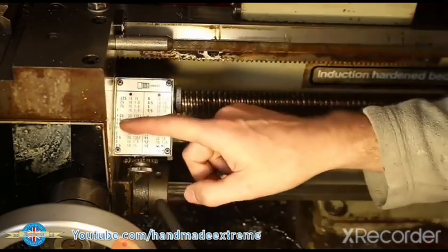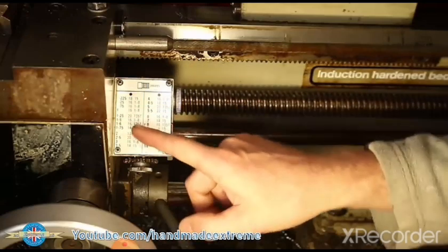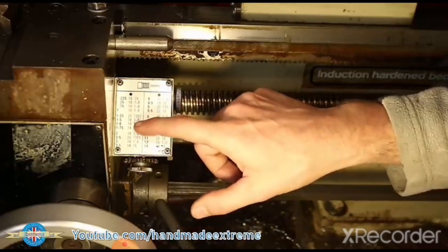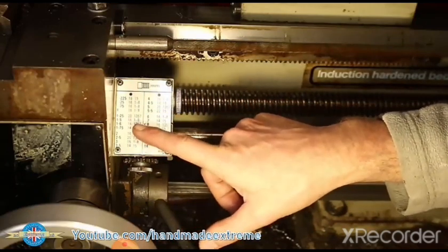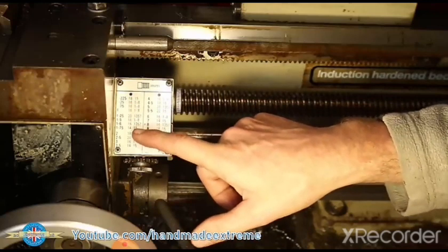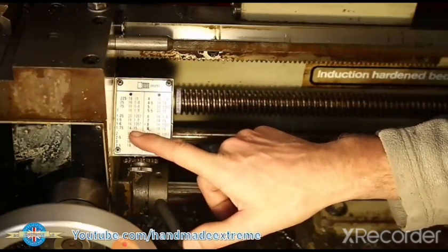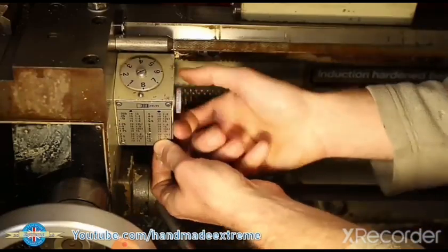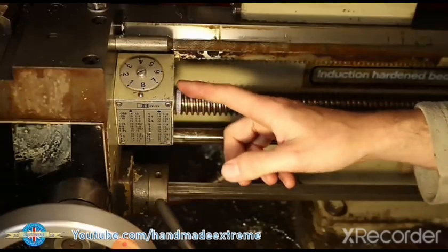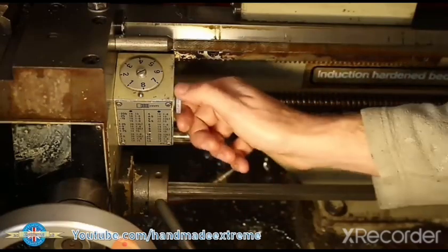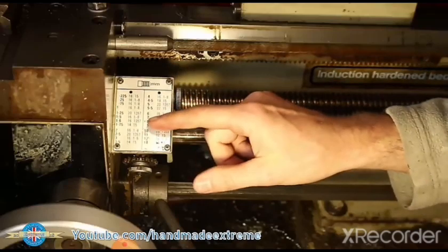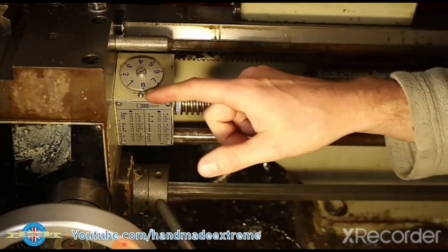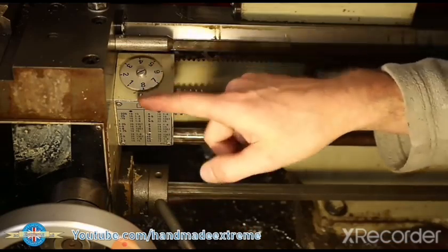So we want to cut a 1.5 millimeter pitch thread. That means we need the gear with 16 teeth, and then there's this little number here, which in this case is numbers 1 to 8. The next one down is 1, 3, 5, 7. The next one down, don't confuse it, it's not 15, it's 1 and 5. What that means is when we want to cut the thread, we can engage the threading by switching on the half nuts, using any of the numbers 1 to 8. So when this is spinning around, we can start our thread when any of these numbers lines up with this little dimple.